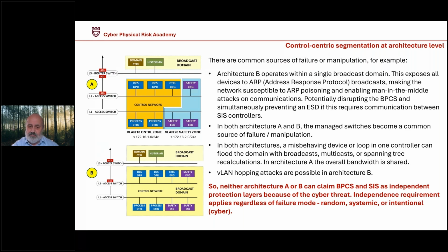So that's a disadvantage. You would never route real-time traffic in principle because that delays traffic. But in this case it's okay because it's not highly critical traffic. What you typically do with the connection between the DCS operator station and the safety station is monitor the safety status, maybe have some additional information from inputs from the safety system, and in some cases you might want to override some safety instrumented functions temporarily for maintenance.